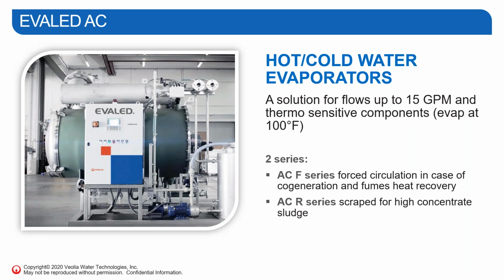The next model is the AC. So this is hot cold water evaporators, and this works fairly similarly in terms of the model options to the heat pump. You have your AC F series, which is your forced circulation, your AC R, which is scraped. Same concepts with the 30% solids versus the 45 to 50% solids. The biggest difference with this model is that we're now able to go up to 15 GPM, so it's a bit bigger. We're still using the strong vacuum to evaporate water at around 100 degrees Fahrenheit or 40 degrees Celsius.